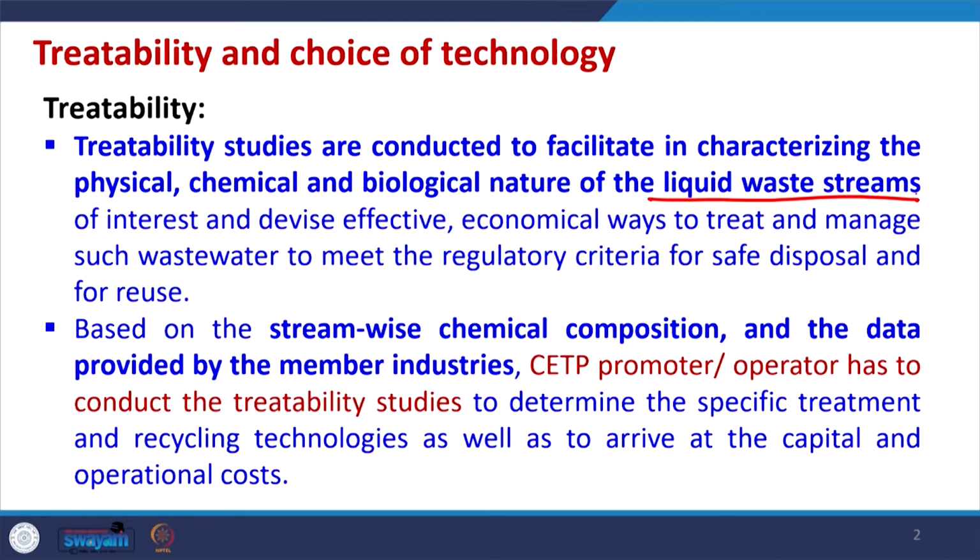Treatability studies have to be conducted to characterize the physico-chemical and biological nature of the liquid streams generated after combining all the different streams from different industrial clusters. Depending upon the stream-wise chemical composition, we may have a heterogeneous cluster, where the streams vary entirely in chemical composition, or a homogeneous cluster, where the composition will not fluctuate that much.